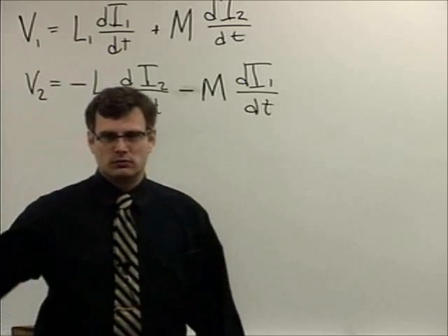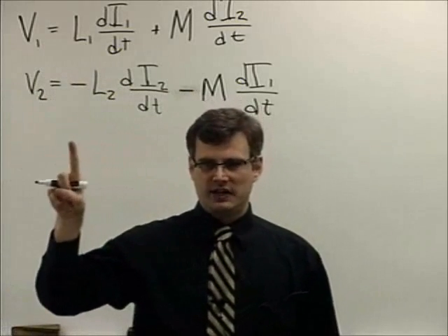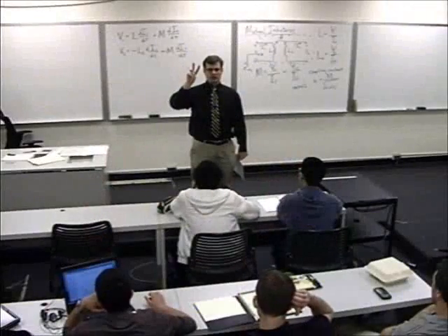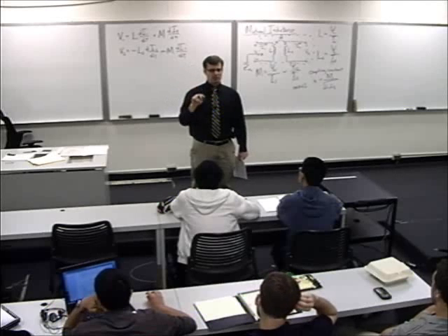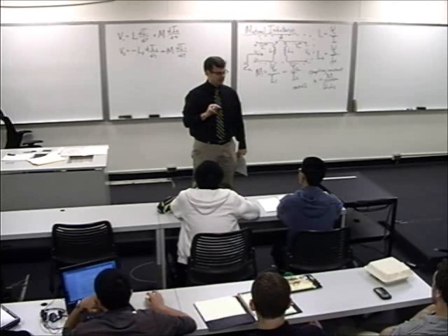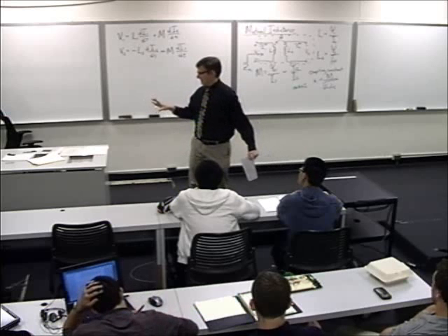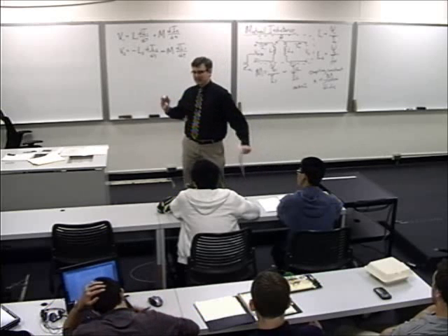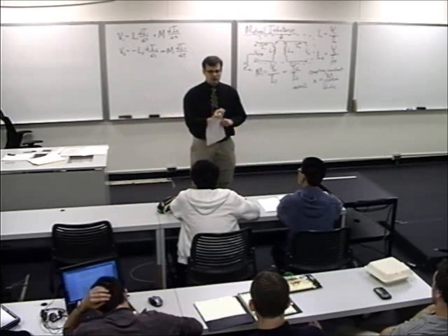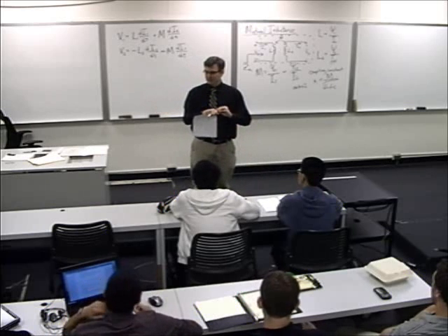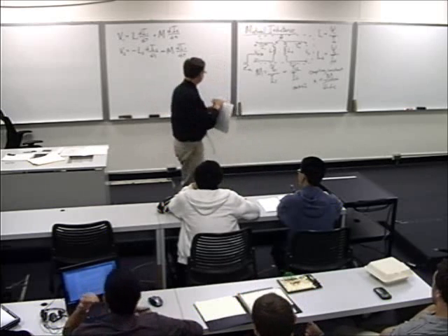So what I'm going to do is convert this to the phasor domain. We're going to rearrange it, put it in matrix form, do some manipulations, and then we're going to back out what the Thevenin equivalent impedance of this is. And then everything will make sense. And you'll be able to model any type of system that uses inductive coupling.